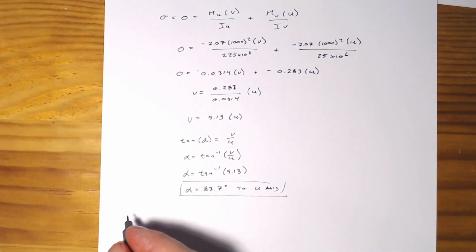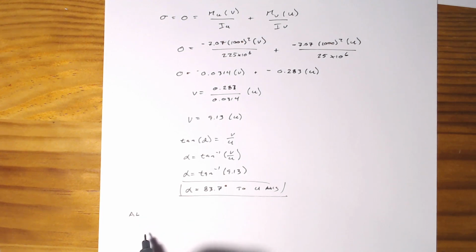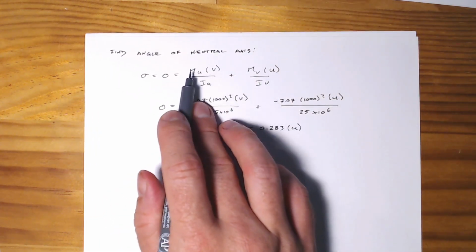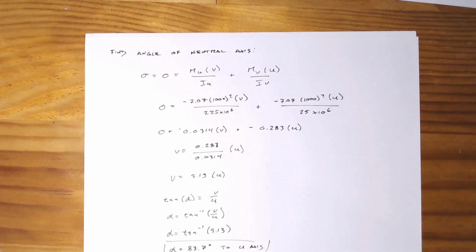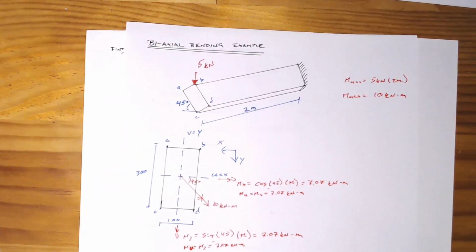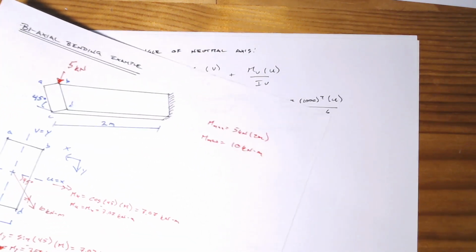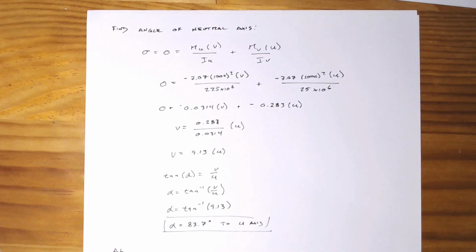And again, alternatively, we can use our ratio of our moments of inertia and the fact of the applied angle, which is really just doing the same thing. If we already know what the applied angle is, these are effectively the components of it, broken down based upon that angle. I just want to show you that it's giving you the same answer.